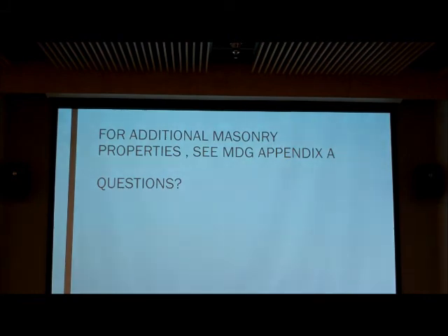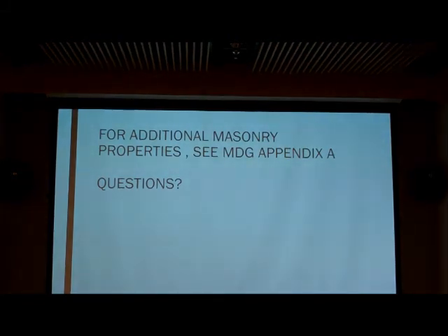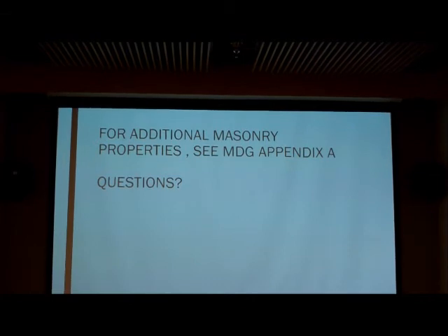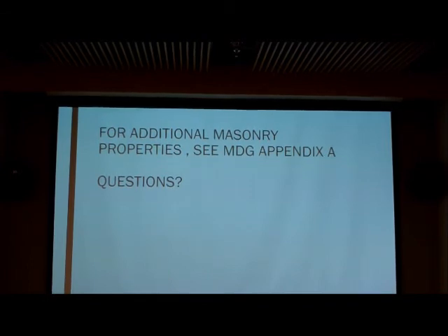So they're large blocks, but they actually don't weigh as much as you would expect. There's a table, and I don't know if it's in that textbook, but there's a table that tells you how much a wall would weigh per how many CMUs, what type of grout you're using, if it's fully grouted, so then you can see the difference in what it weighs with and without grout. Okay, very nice. So then you don't have to add it all up and weigh the whole wall. It just gives you.